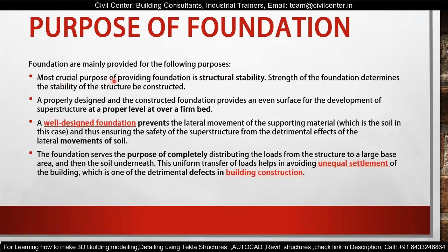First, the most crucial purpose of providing foundation is structural stability. The strength of the foundation determines the stability of the structure to be constructed. So let's understand this structural stability. Whenever we have superstructures and the foundation is absent, that means wherever the soil is weaker, or you can see that the soil bearing capacity is low, then the column will penetrate the soil and your structure will go into the soil and it will definitely affect the whole structural stability.